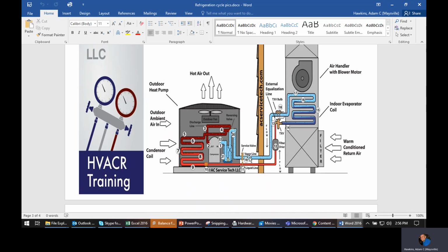I do that too. Like, if I stick my hand to that, I'm measuring superheat. I just maybe don't know the exact number, but that's what I'm doing. So when you measure superheat, you're measuring the latent heat change between the saturation point and that line, and that line's going to get warmer. So once it superheats, we're going to be able to measure that temperature with a thermometer, and that's why we just strap a bulb to it. Now, that's the same way your TXV works. It straps a bulb to that line, and it uses that bulb to help it know when to open and close.